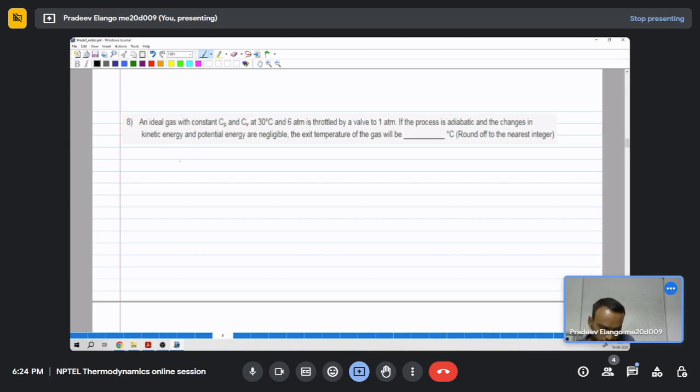So now we have change in internal energy is equal to Q minus W plus enthalpy of the mass coming in, that is m_i h_i, minus enthalpy of the mass leaving out, so m_o h_o. So now for a throttle device, the change in internal energy is 0 because it is occurring at a steady state, and there is no heat transfer, there is no work transfer. We are left with only the enthalpies of the mass coming in and out. At steady state, both the mass should be same, so we will have enthalpy h_i is equal to h_o.